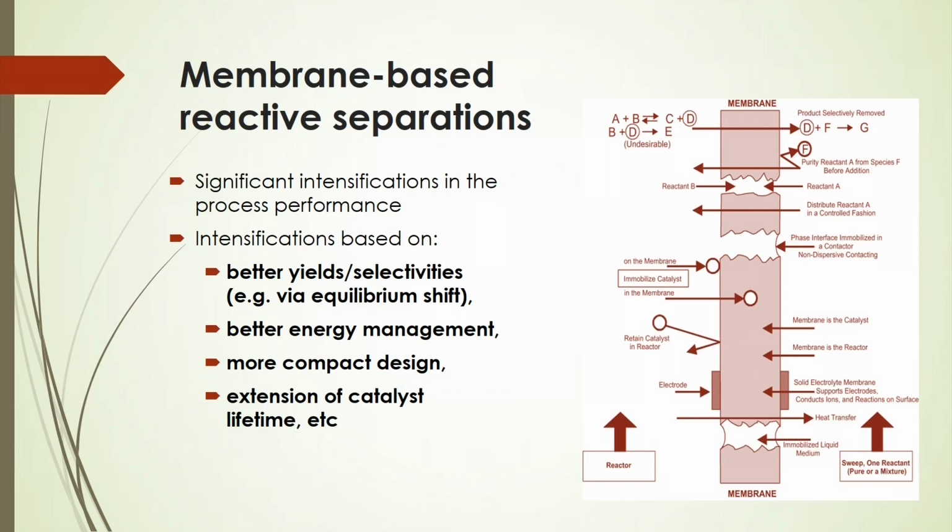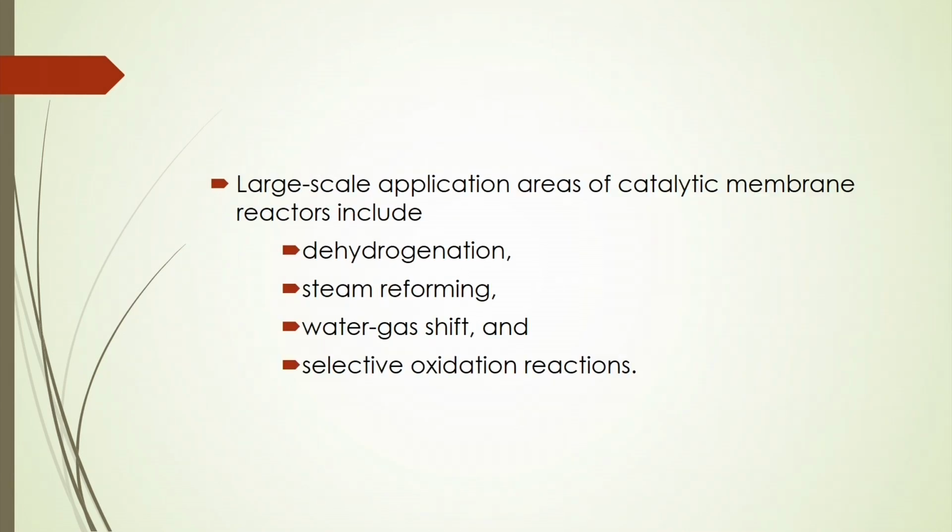In this case, this hybrid separation, the membrane aided process, is significant because it gives better yield, selectivities via equilibrium shift, better energy management, more compact design, even extension of catalyst lifetime, etc. So, based on this you can have significant intensification of the process by the membrane.